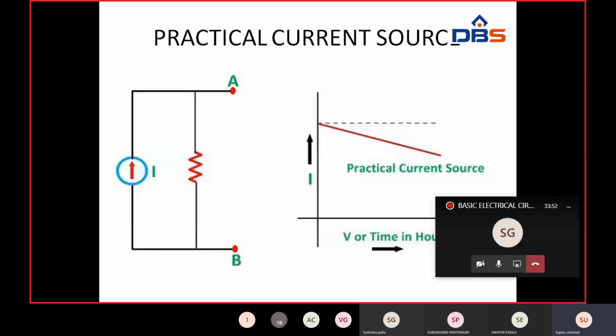These are resistors, inductors and capacitors. These are all called lumped elements. Otherwise, it is called a distributed element. That means if the size of the element compared with the wavelength is not small, then it is called a distributed element. Long transmission lines are nothing but distributed elements.